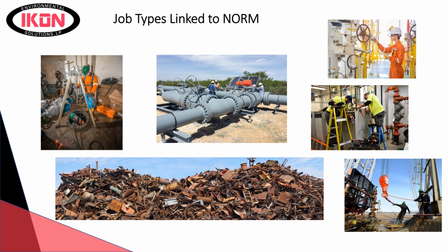And so you get those trapped in your pipeline rouge filters, but that doesn't mean that every time you find pipeline rouge, it's always going to be radioactive. And it doesn't mean if you don't have rouge, it's not going to be radioactive. In fact, the ones that don't have rouge, a lot of times are higher in radioactivity than the other ones for a couple reasons. One, you're plating out pure lead-210 on the inside of that pipeline component.